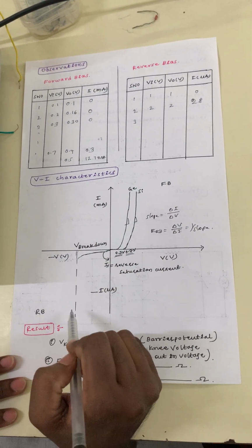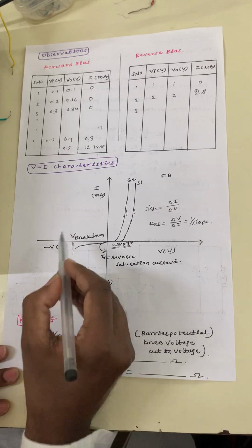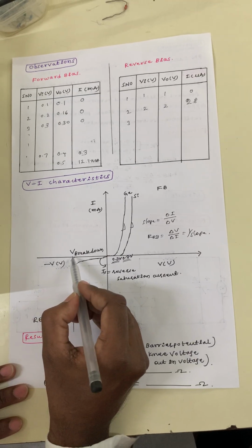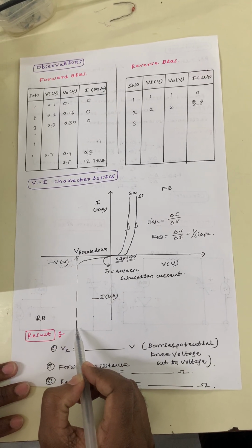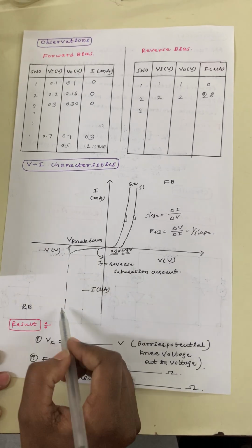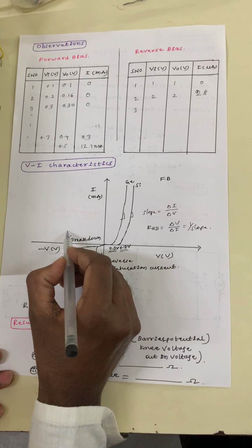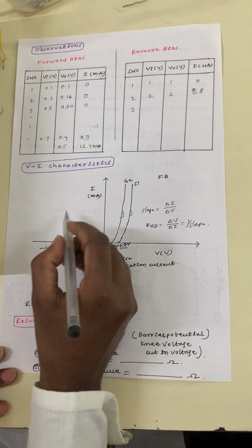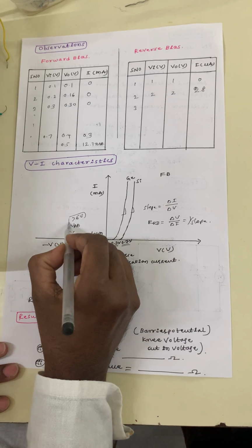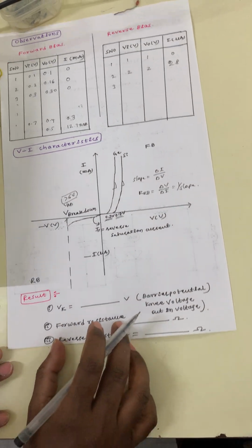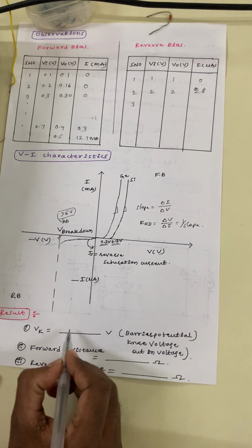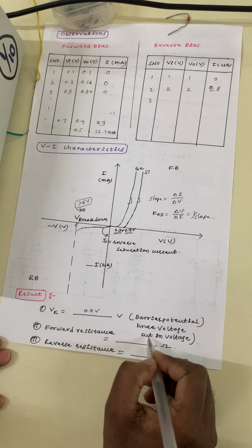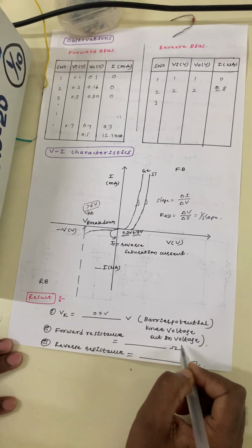Now you are able to take the graph. What is that graph? The graph will come like this. Wherever the sharp fall comes at a particular voltage, where the current falls sharply, we call that the avalanche breakdown voltage. Around greater than 6 volts this avalanche breakdown will come for the junction diode. As we already discussed, the 0.7 volts is the barrier potential voltage or knee voltage or built-in voltage.